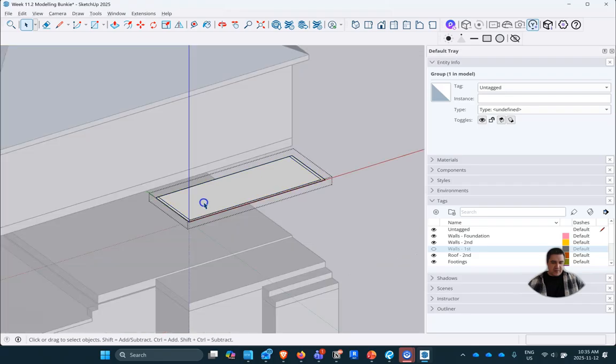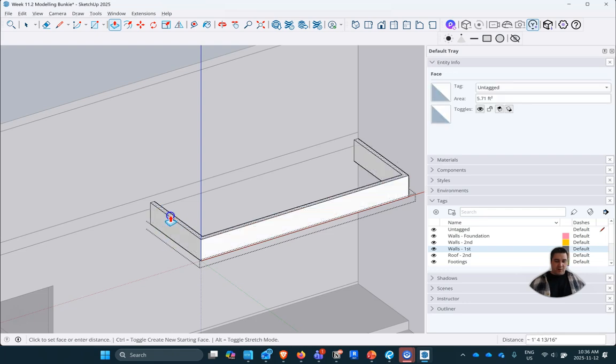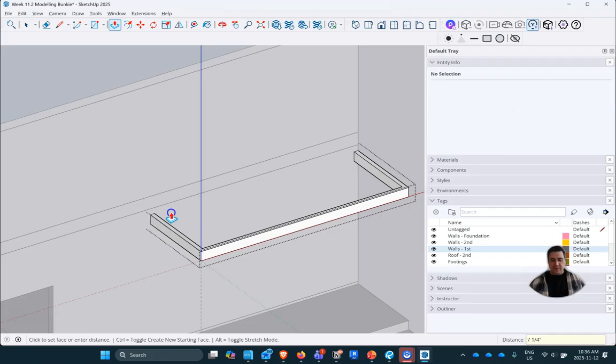And let's edit our group here. And I'm just going to bring our walls back. And so with this, we're not putting our ceiling here. Our ceiling is actually going to be a little bit higher. We just have our beam here. So I'm going to remove this back line. And we're going to extrude this beam up our 7.25 inches, which is our 2x8s. So that's our kind of ring beam going around the perimeter of our porch. The next thing I want to do is the actual roof itself.